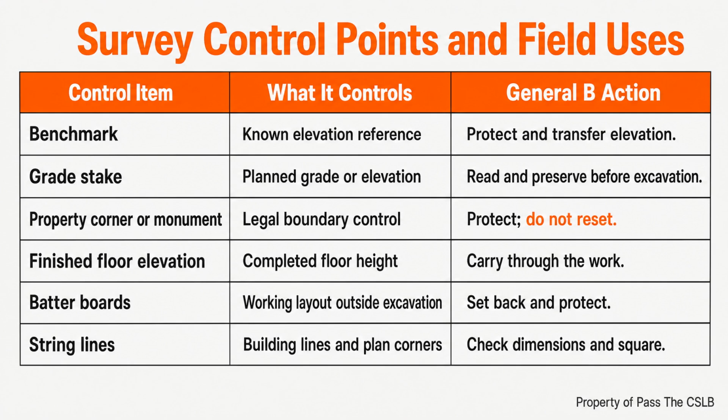The reference table on screen separates the common site controls by function. A benchmark controls elevation. A grade stake communicates a planned grade or elevation. A property corner or monument controls legal boundary information.